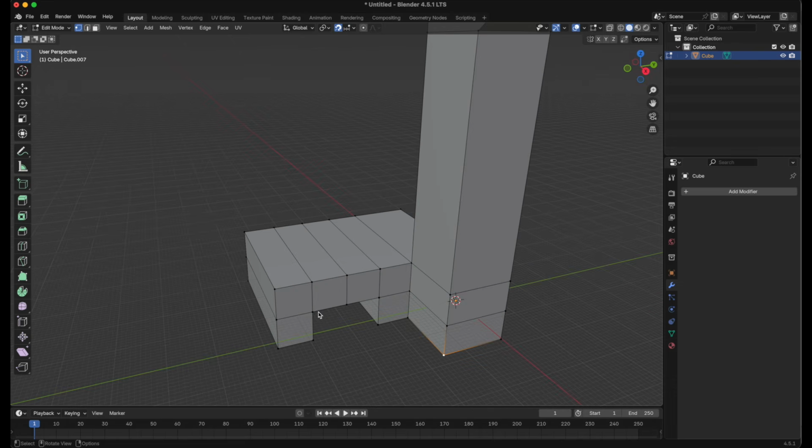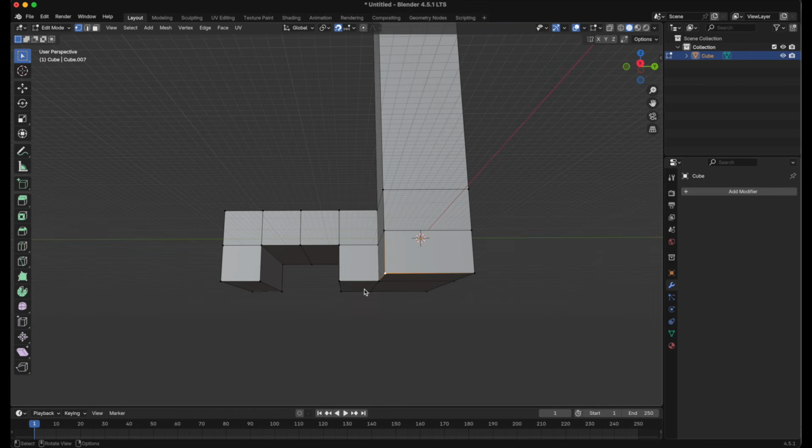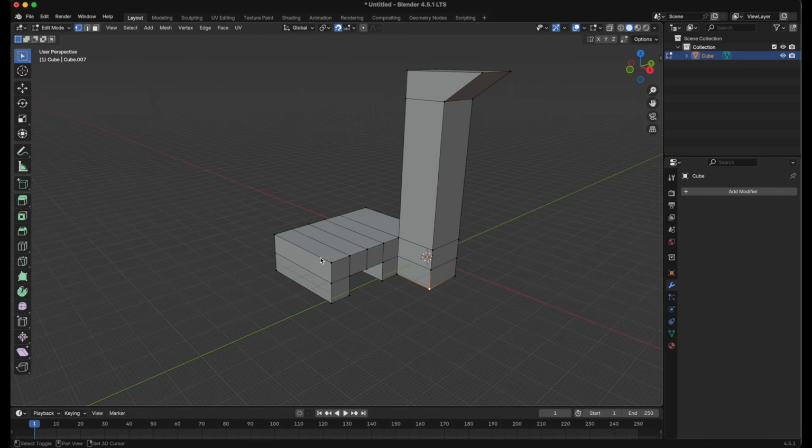It uses the tensile strength of the filament. So as it's going across here, it'll build the edges and then kind of fill in like so. And then you can print perfect overhangs like so, without needing to use supports, and this is called bridging.